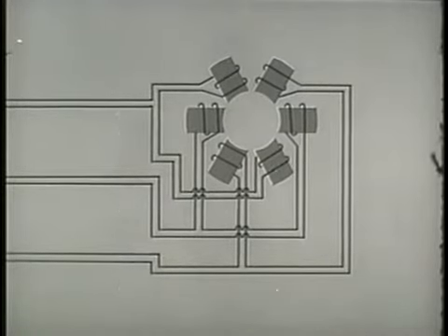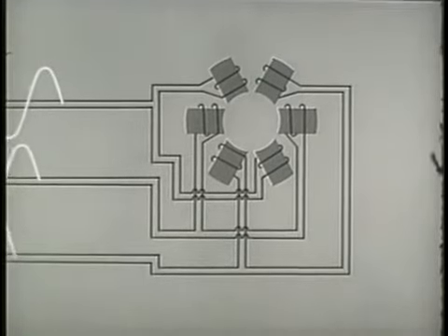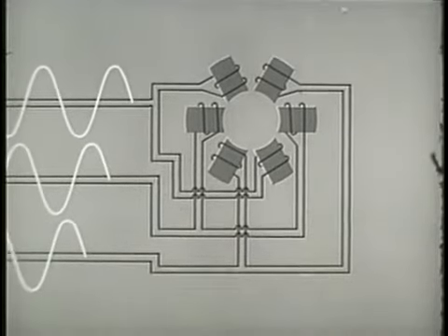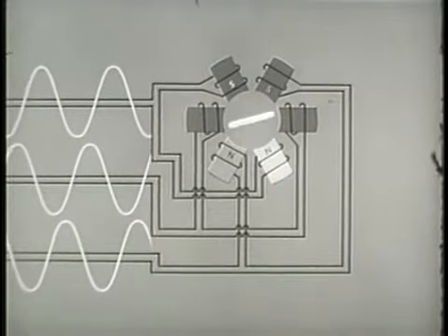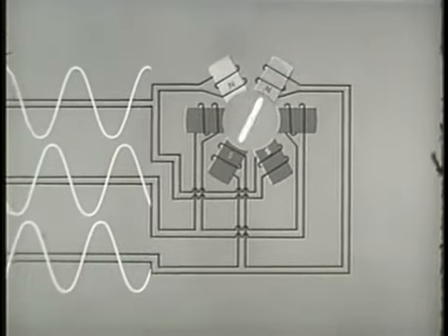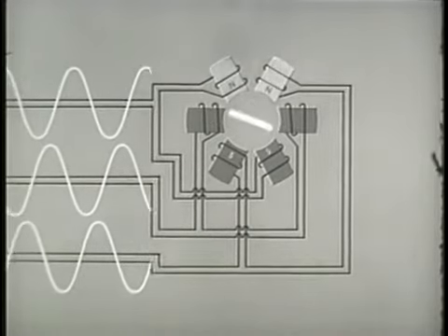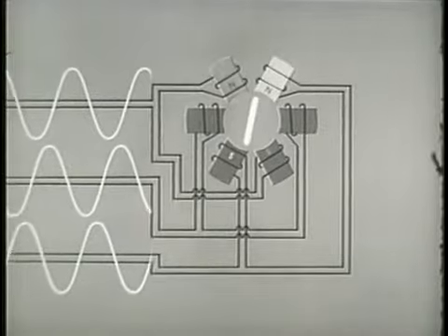These 3 pairs of conductors, 1 pair for each AC phase, supply the field. Because of the time difference in the 3 phases, the poles will be energized in successive order, thus rotating the field electrically. Since the rotating field is cutting the rotor, it will rotate in the same direction as the rotating field, but at a slightly slower speed.